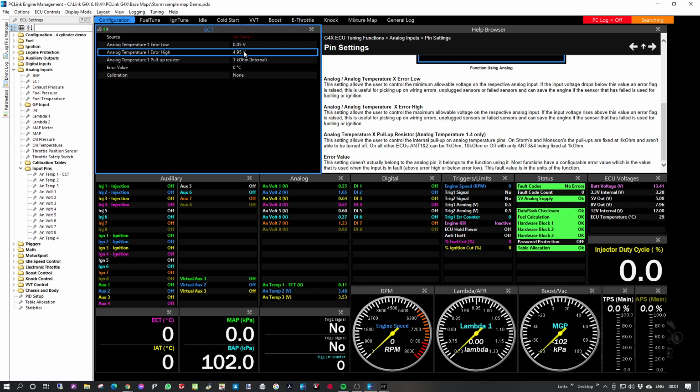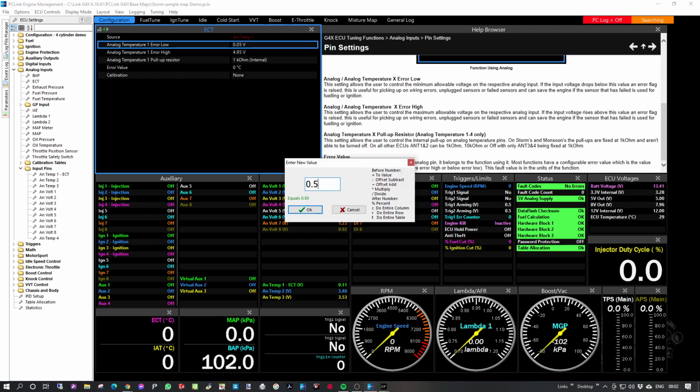If you know the characteristics of your sensor, always set these a tiny bit towards the very end of each sensor calibration, and you'll get a bit more accuracy. If the sensor stops at 0.5 of a volt, well, set it at 0.4 of a volt. It will just give you more failure mode.